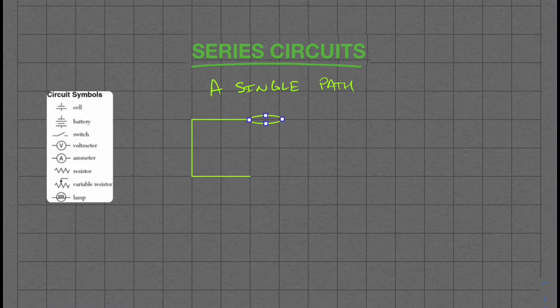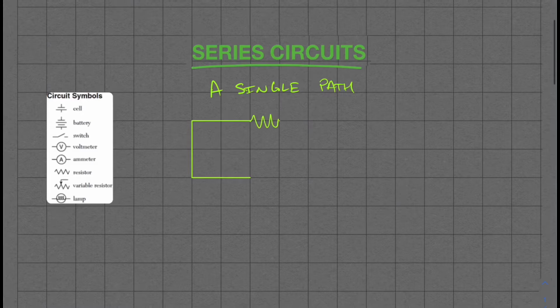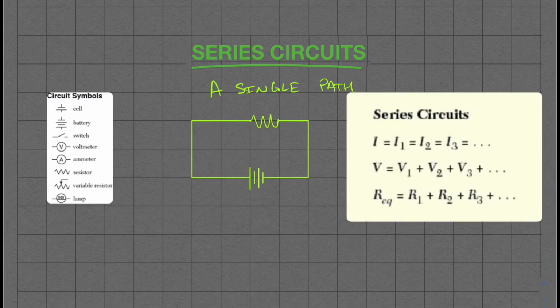The thing is, with drawing circuits, you have to be very precise and very careful that everything is nice and neat and organized. That's the whole point of a schematic diagram. So you can't always get credit if it is a little sloppy. Just take your time as you're drawing these things so that you get it as close to these symbols as you can, and that all your things meet at right angles or as close to them as you can.